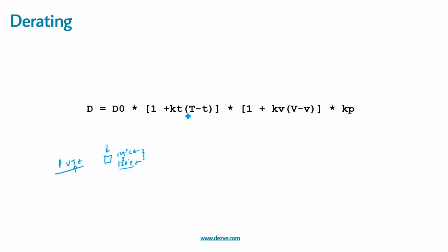So these derates are not to be applied across large ranges. Suppose I measure something at 125 and then want to derate it for 75 degrees centigrade. That would not work, correct? For a slight variation of temperature, voltage, and process, this was the delay value extracted via the lookup table, and then based on the derate value, these are the constants, the derate scaling factor, which is used.